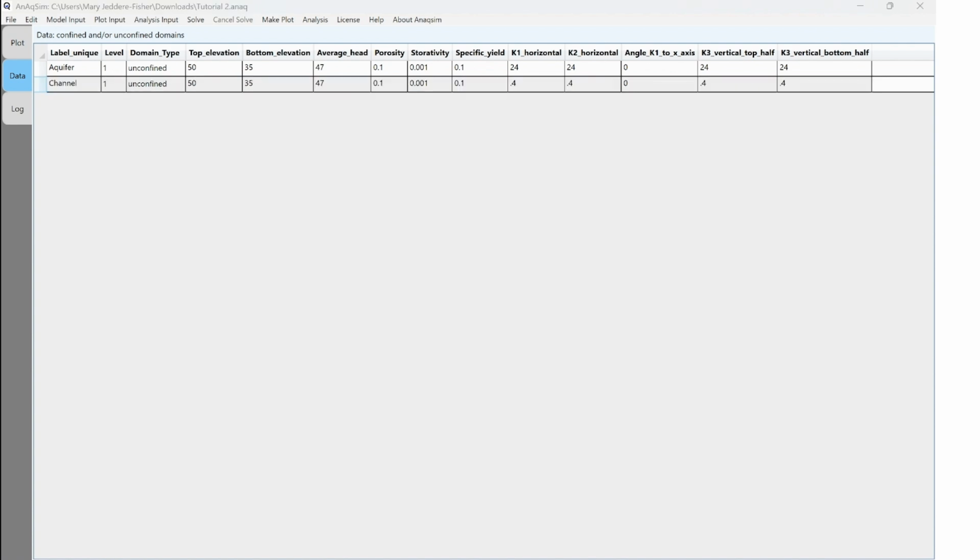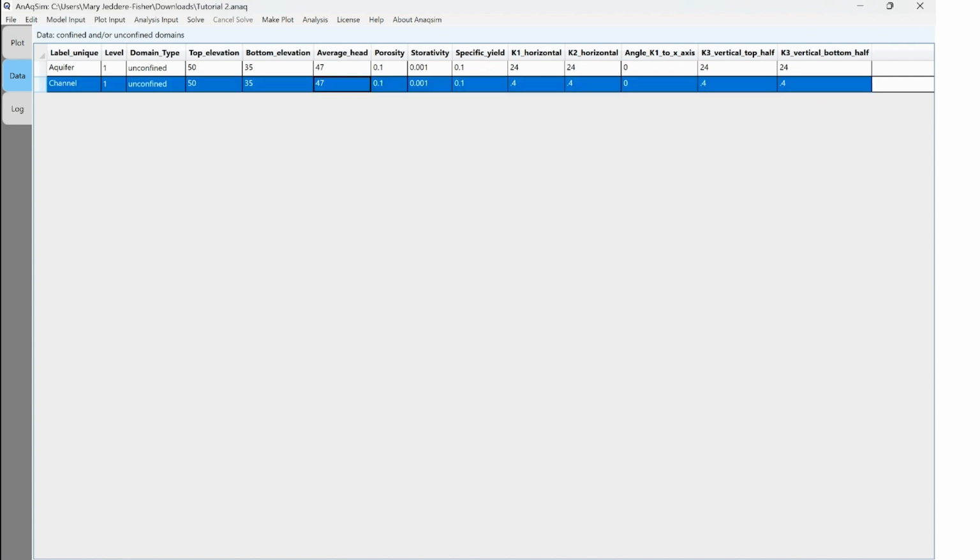After creating the domain, our next step is to define the model boundary. This sets the horizontal extent of your simulated aquifer. In this example, we'll define boundaries for both our main aquifer and our silt channel. Let's start with the main aquifer using the HSEG boundary generator again.